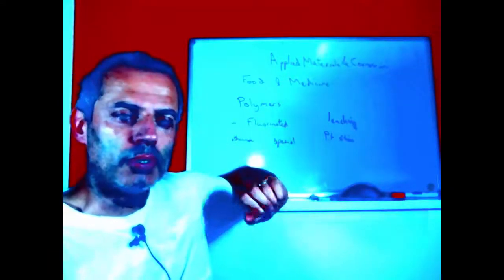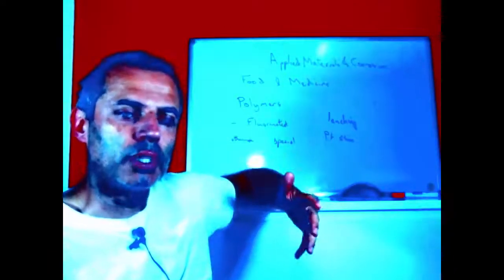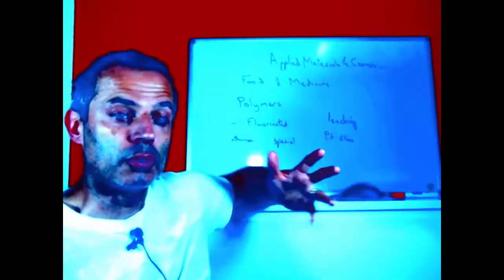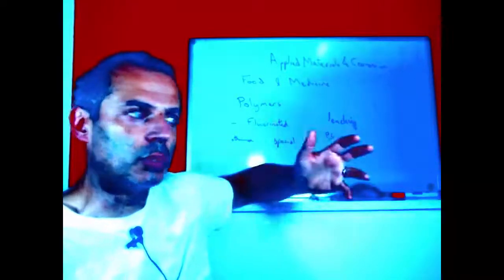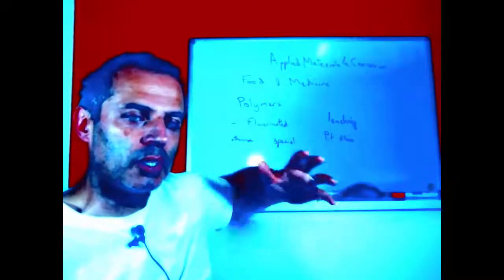Very often, however, if you make a device that contains many materials together, it becomes difficult to sterilize it because each one has its own requirements. So many polymers don't like hot steam. Many organic materials don't like oxidizing agents. Metals are not so good in combination with salt and oxidizing agents and water and light.